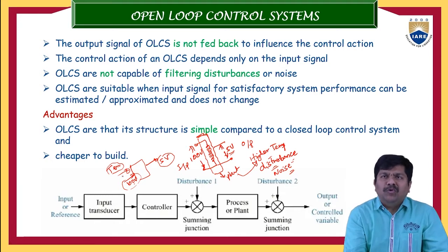Now the plant will observe two inputs. One is the actual input, 100 volts, and the other is the temperature variation. Not only temperature, but other environmental variations too: the plant will see all of these as inputs. Of course, those are unwanted inputs, but in a practical system such inputs will always be there. So along with the actual input, you have to analyze how many inputs act. All these inputs, 100 volts and the other disturbances, will influence the output.